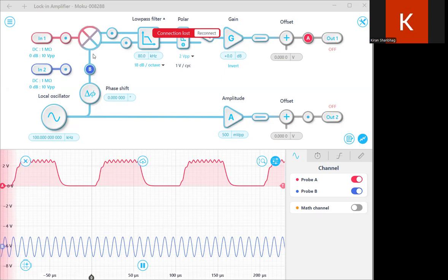What's going to happen is the local oscillator at the receiver. The reason why we use this lock-in amplifier is that Moku has a lock-in amplifier, and in demodulation here we get a frequency multiplier facility. Then it's kind of a PLL where we can adjust the gain, the phase and the offset, which we are not using. We will be using the local oscillator. The same frequency has to be given: whatever local oscillator frequency we have given there, we should give here also.